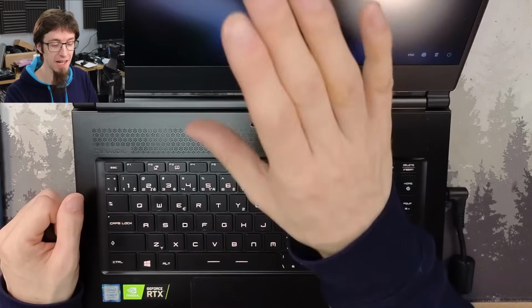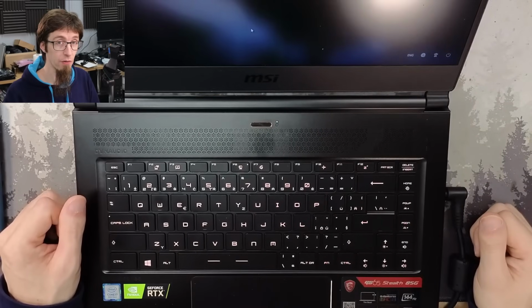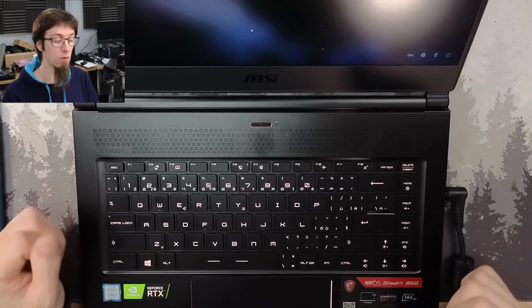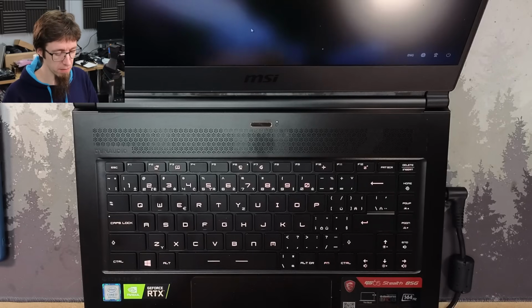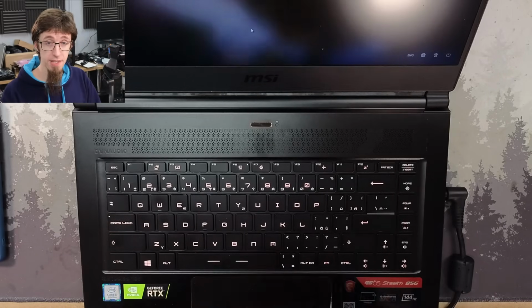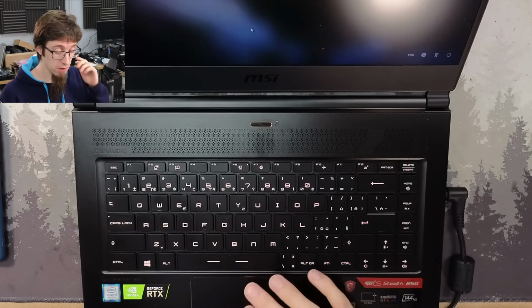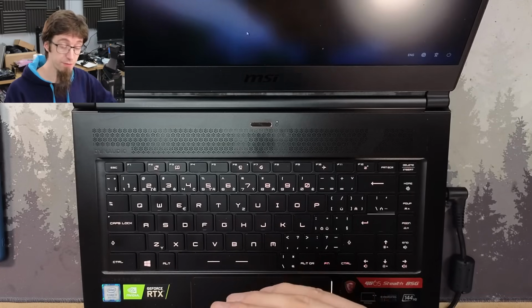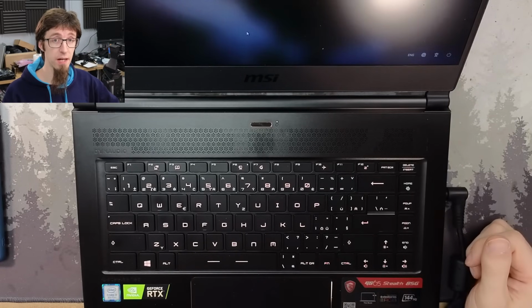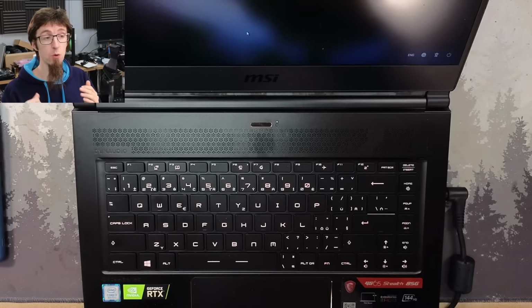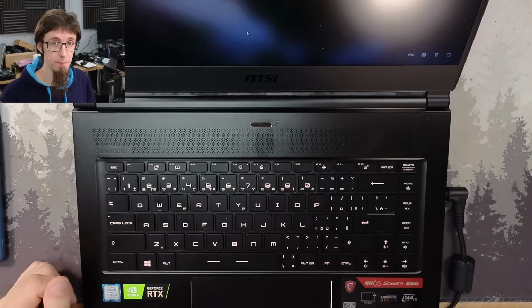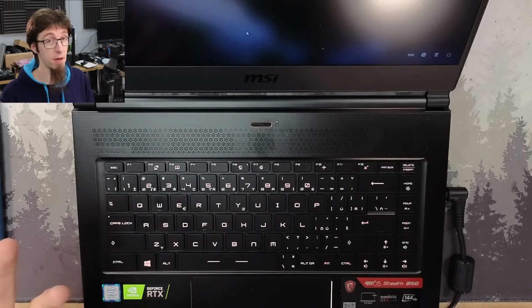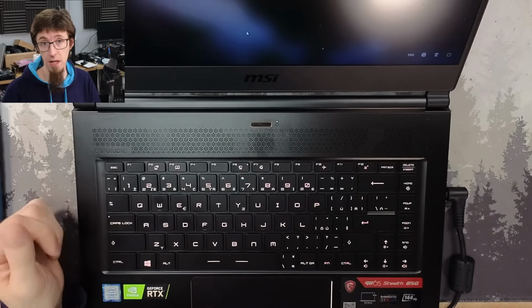There's no way that a laptop LCD is using more power than that. And if there is more than 45 watts going into the screen, we should probably blow that guy open. So that's not something I'm going to worry about. Past that, we've got a good fix there. I was a little bit worried when this one came in because while it was very obvious that we had an exploded inductor, you must always ask yourself the question, why did the thing explode? Because an inductor doesn't have a path to ground, so why did it blow up?